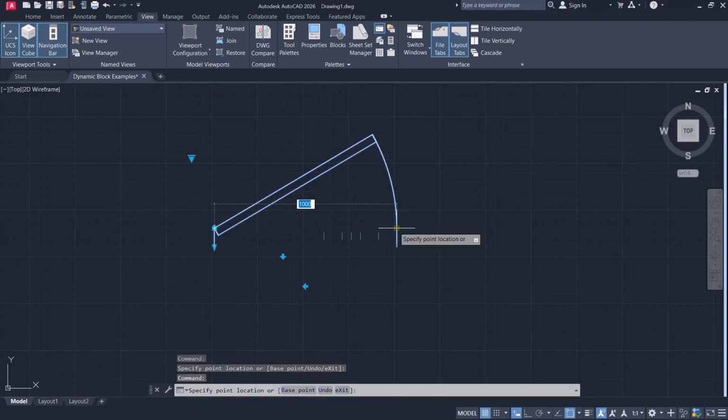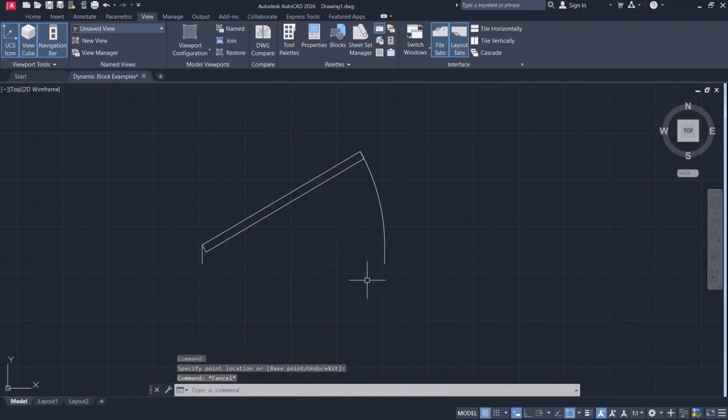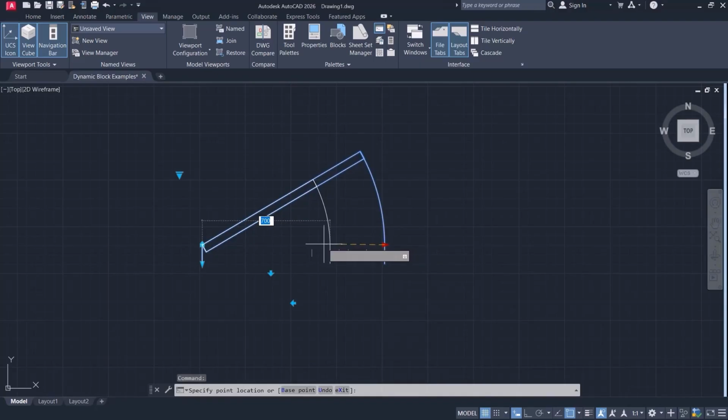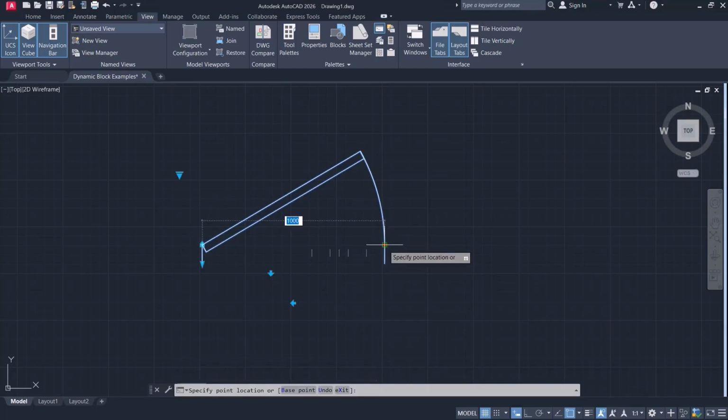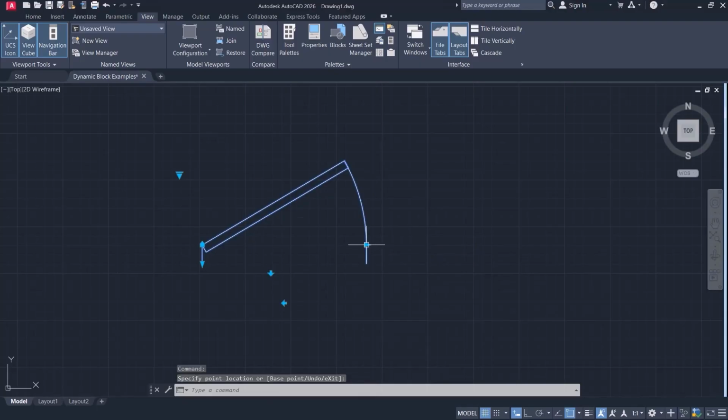I can only scale this to certain specific dimensions and sizes. Now it also has 60 centimeters. That's a really great feature. The standard doors we usually have range from 60 centimeters up to 1 meter. Of course, there are larger ones too, but room doors are usually at most 1 meter. Instead of scaling this myself or having to use the scale command, set a base point, and adjust it relative to my object, then go and scale it, I can easily move it with just one button.